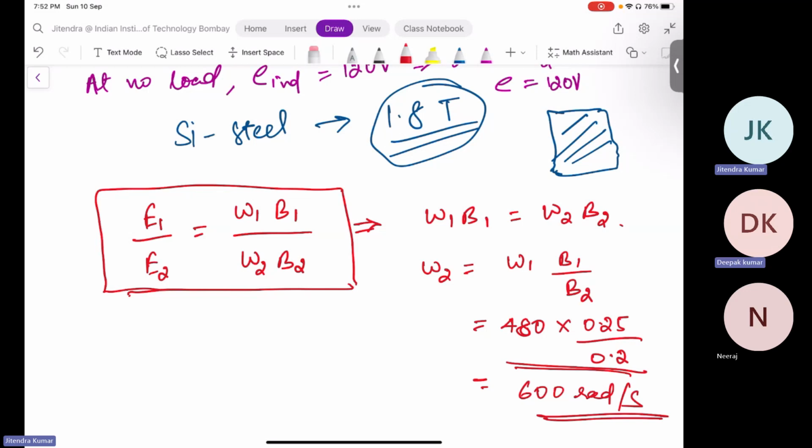No, sir. But I would like to have an answer. Okay. First, I would like to have an observation from you guys. What did you observe from this part, specifically, last part? When the flux density decreases, the no load speed increases. Yes. Basically, the philosophy to increase the speed is that you have to reduce the flux.